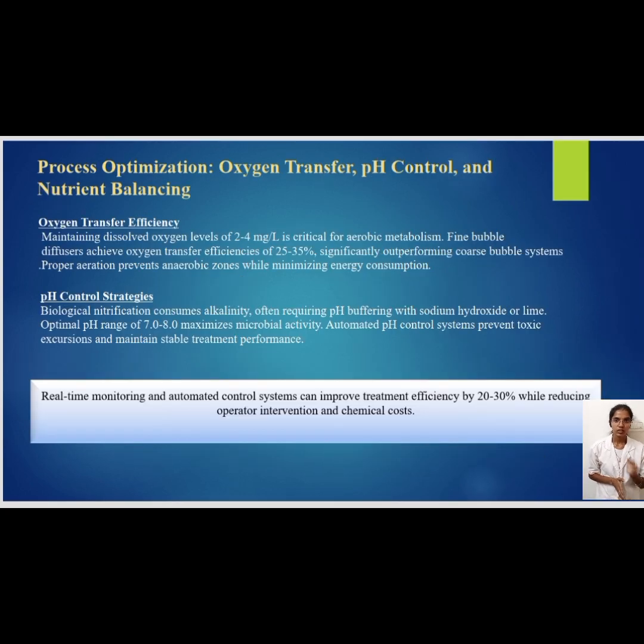Three things must be controlled: 1, the oxygen, 2, the pH, and 3, the nutrients. 1, the oxygen: keep dissolved oxygen around 2 to 4 mg per liter. And 2, pH: microbes work best at pH 7 to 8. And next point, chemicals may be added to keep pH stable. And 3, nutrients: microbes need a balanced food ratio. BOD to nitrogen to phosphorus equals 100 to 5 to 1. Leachate often needs added phosphorus to stay balanced.